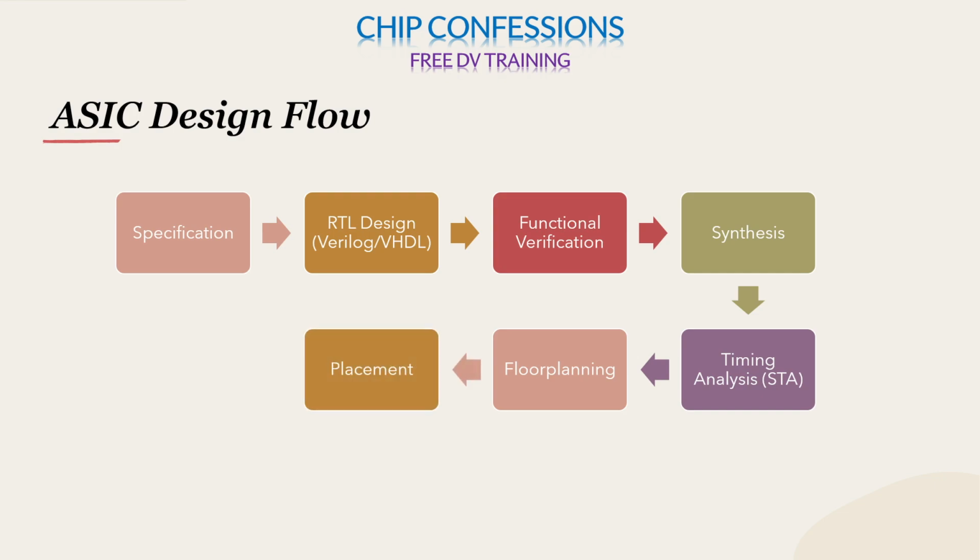And then we will go for placement. What we will do in placement, once planning is done, is we will place those blocks. On that we will be defining a layout of the chip, and layout is nothing but, I can say, the area of the chip, and within that area, as we have planned, we can roughly compare it with building a house: where should the kitchen go, where should the room be, where your hall should be, where your puja room should be, like how we plan.